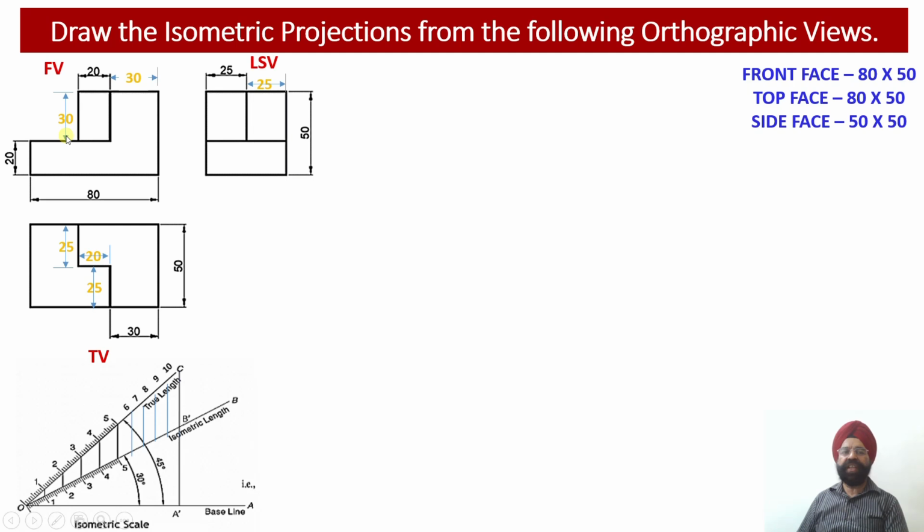And third information is available to me about this segment from the side view. If I look at this segment from the side view, please check, I am looking at this from this side. You see there is one rectangle which I am getting corresponding to this vertical edge, which is equal to 25 by 30 millimeter.